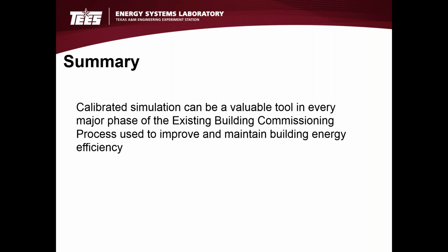Okay. Fundamentally, what we are using is a local implementation of a simulation process that was developed by ASHRAE many years ago called the Simplified Energy Analysis Procedure. This procedure has a lot of detail on secondary systems and primary systems, and very little detail on envelope behavior.